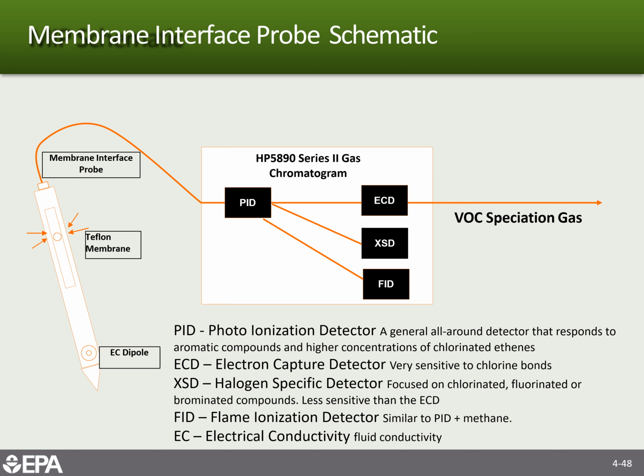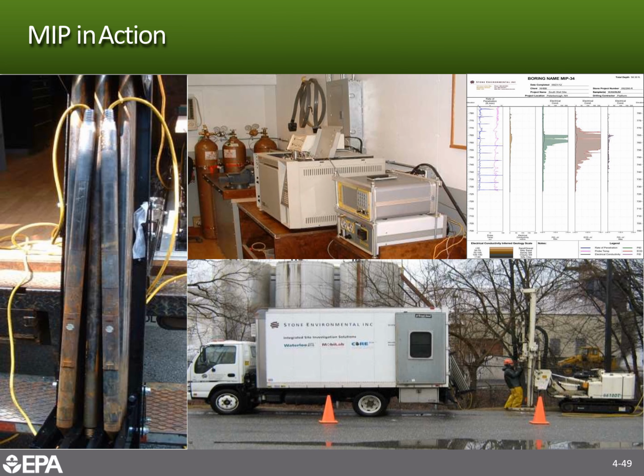And then this electrical conductivity, that usually correlates to your lithologies. So, between the two, you can get a pretty good idea of what's at a screening level, what's going on at your site. This is what that setup looks like.